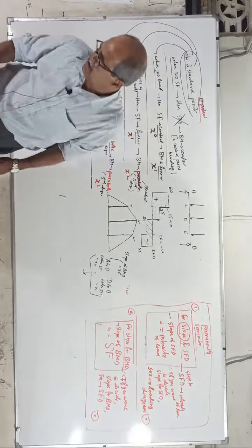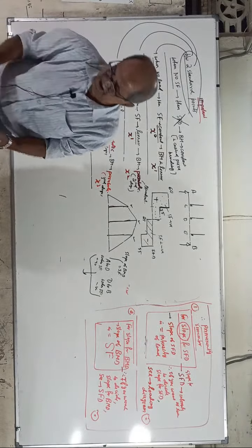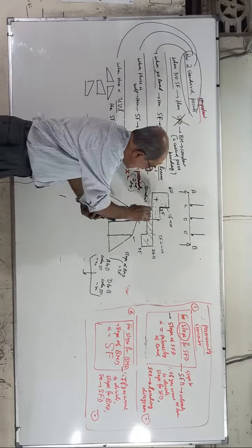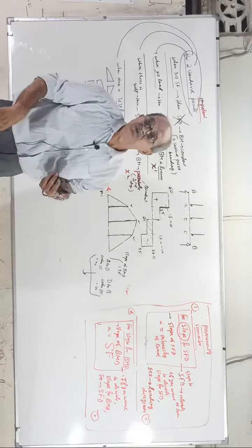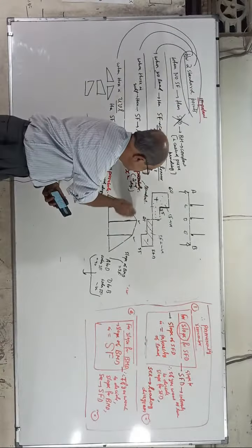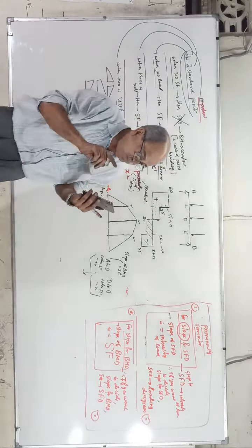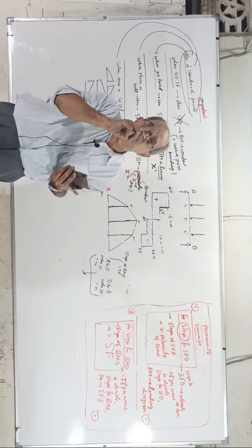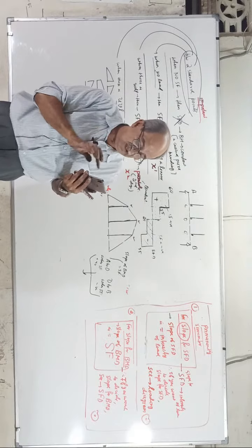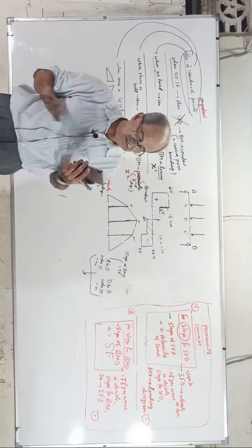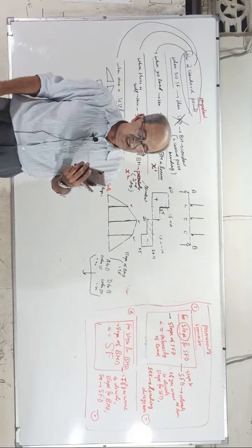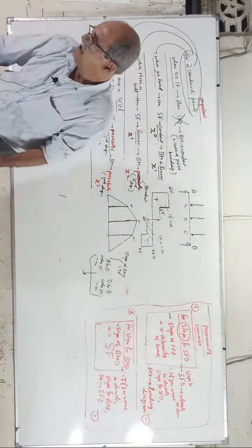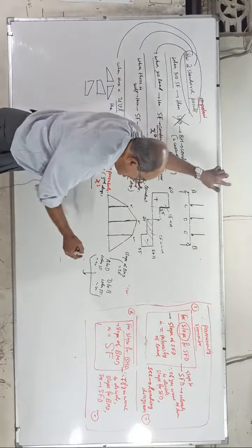They should be what? You can tell at least. This side shear force positive, that side shear force negative. So, slope of BMD this side and that side should be what I want. Don't tell clockwise, anti-clockwise. They should be one word. Just one word. Opposite. That's all. Means they should be opposite.